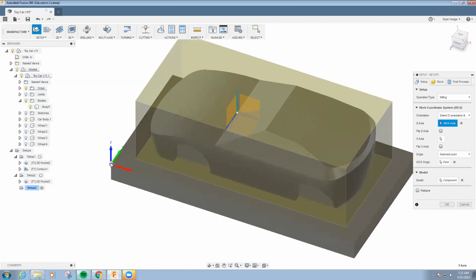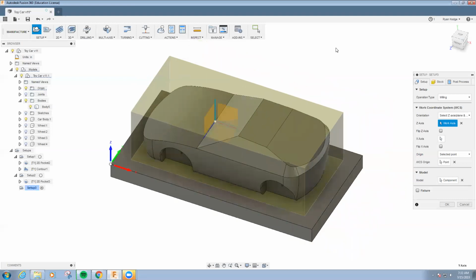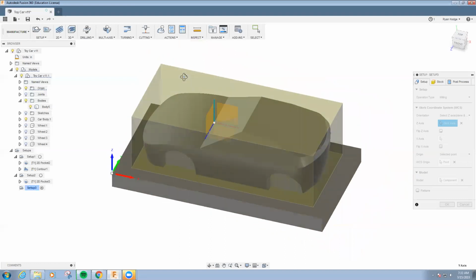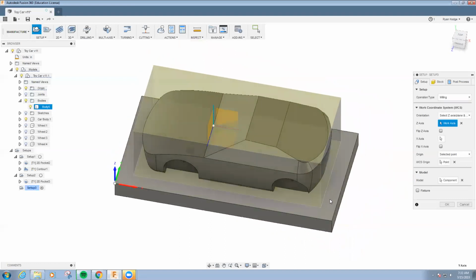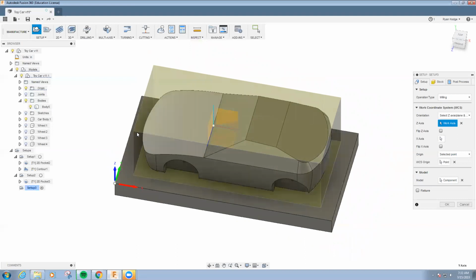We found a glitch in the X-carve that if we touch off to the bottom of the material, there's a glitch in the post that drops the tool into the material on its way out on the very final portion of the run. So I need this point to be up here to be on top of the material. It's not an issue at all on the ShopBot. So I'm going to need to match the size of this spoil board, but bring it up to the top here.